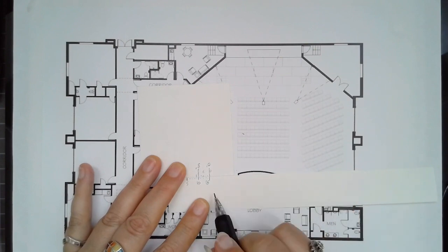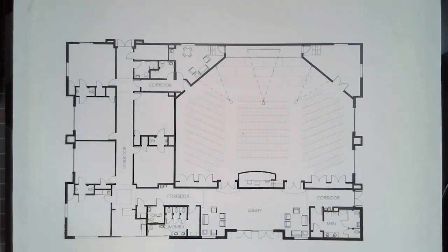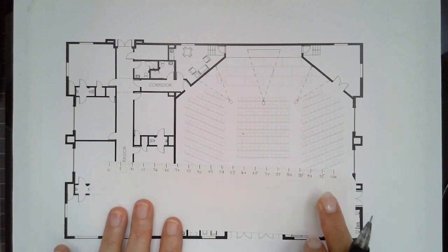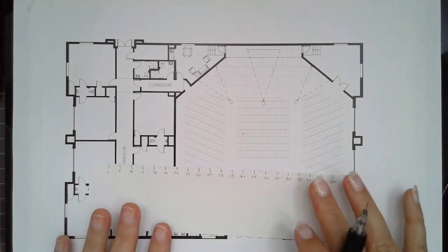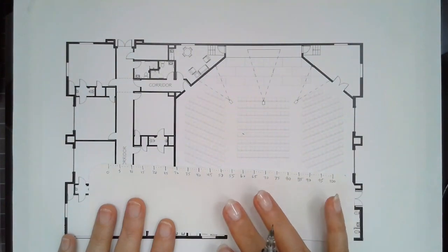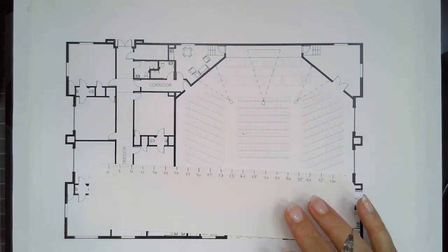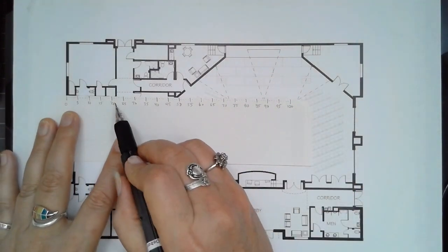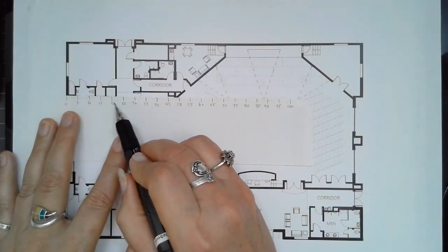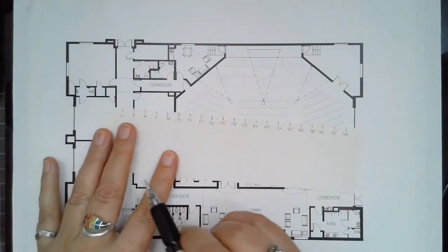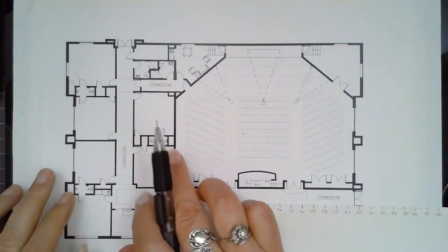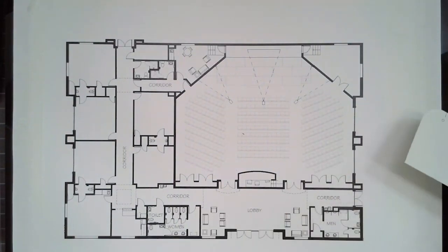So I've already completed that on a separate sheet, and I can use this now for scaling, and this is my standard scale. I can dimension this entire building with regard to that and have my structural framing system align with that. I see I've got about a 20-foot, 21-foot span to the wall on the inside, about 30 feet on the inside, so it kind of makes sense to divide that up into 2 spaces.